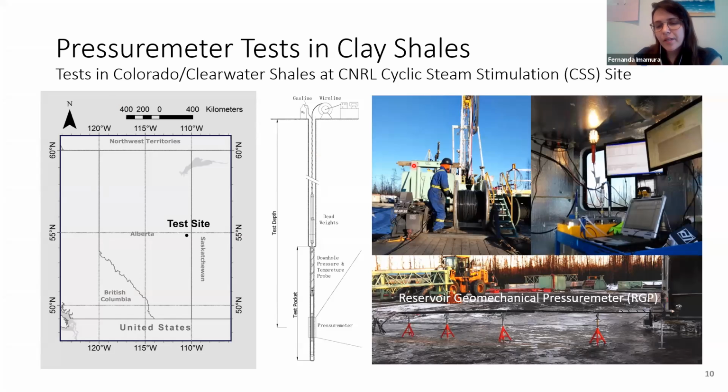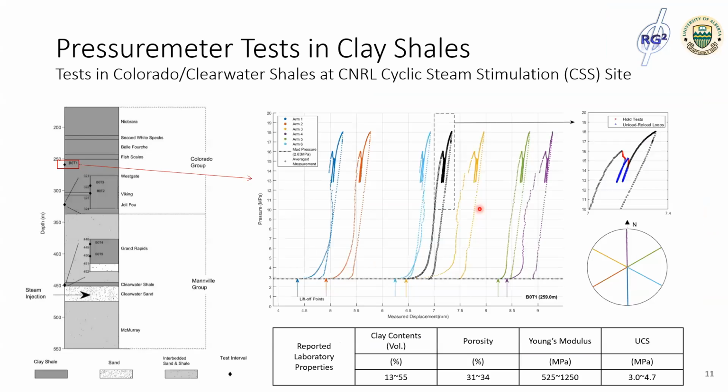So Anna Manderson has another question about unload and reload loops. She was asking if the quantity of unload reload loops affects the data. Would fewer loops for the same pressure range have provided better data? So the answer is no. Theoretically, the unload reload is conducted in the elastic condition because you relieve the stress.